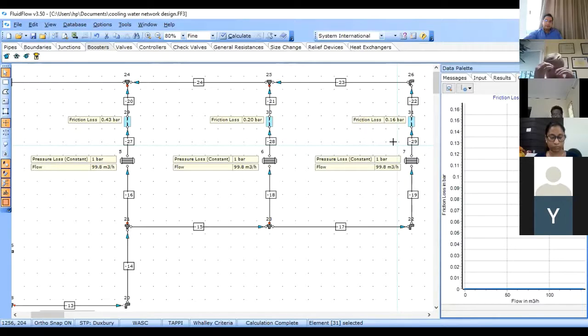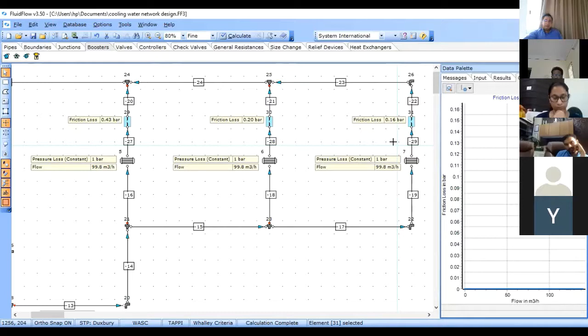And that delta P has happened because of the orifice. Do you really think the system would care how the pressure is being reduced, with an orifice, manual globe valve, or a flow control valve? It doesn't matter, right?